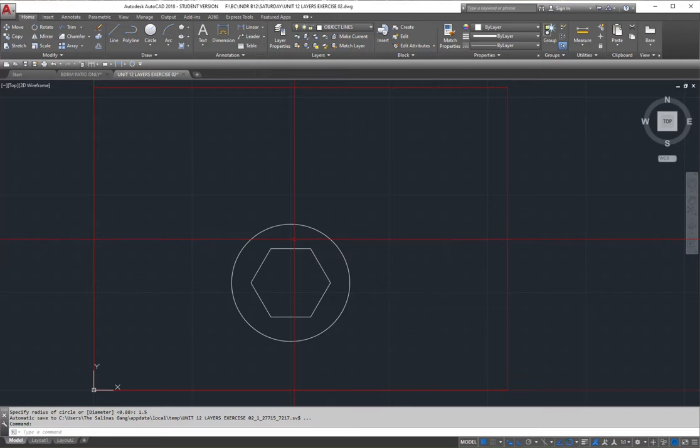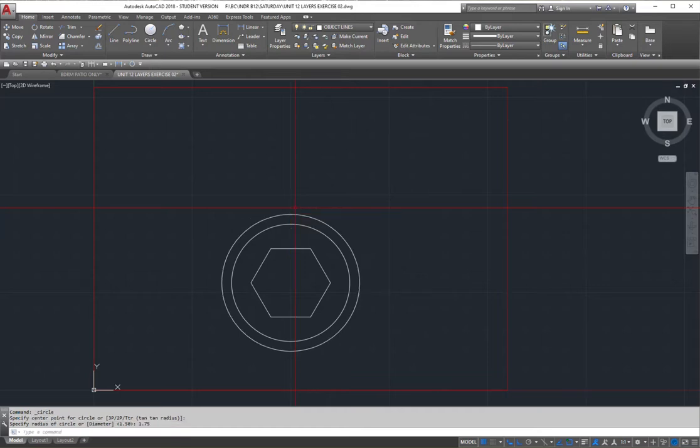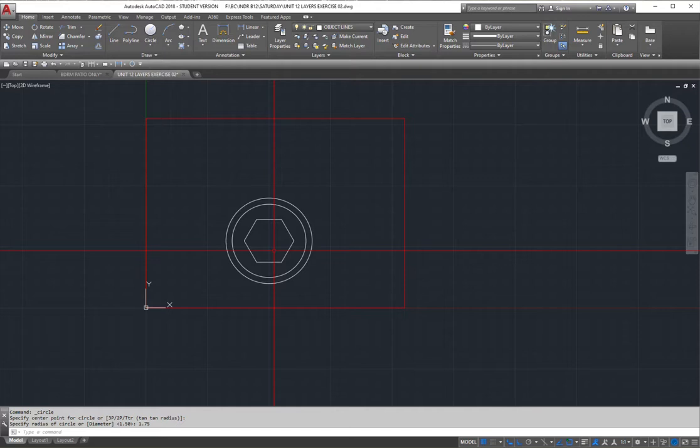And then I have an additional circle with a radius of 1.75. So I simply go to my options, center radius, from the center, a radius of 1.75, enter. Now it looks like I will have some parts right here and some other parts right here. I have to check my measurements: 3 units away from the center I'm going to have another 2 circles, because it tells me the smaller one is diameter 0.625, 2 holes, and the upper part says radius of 0.75, 2 places.